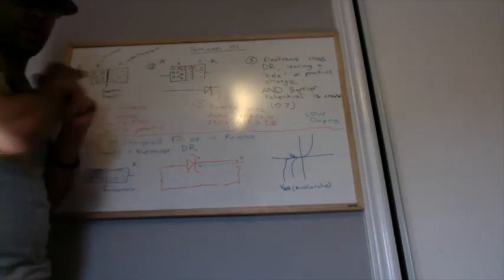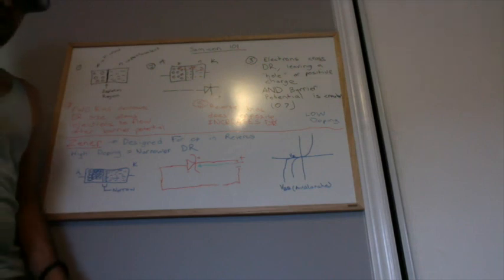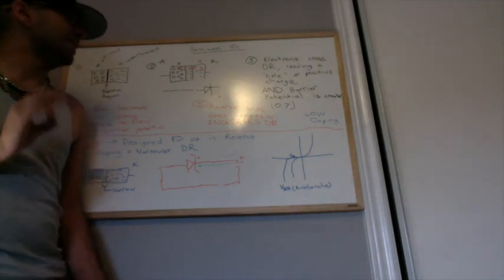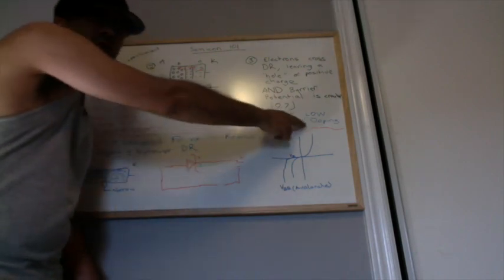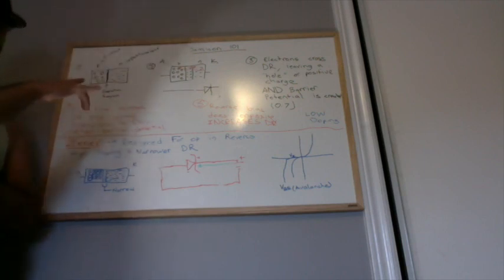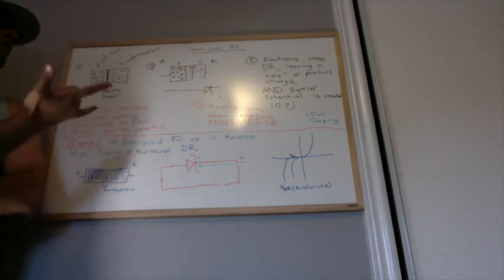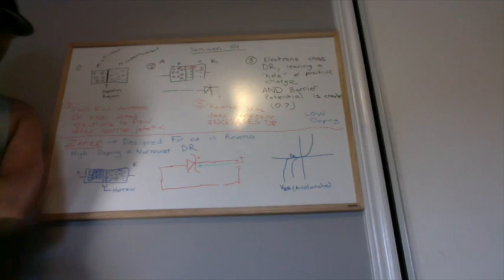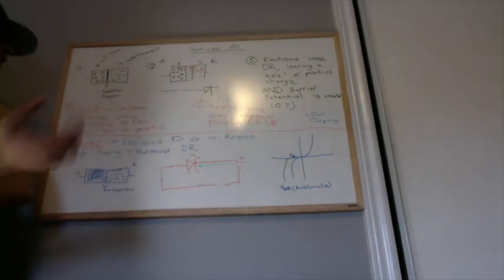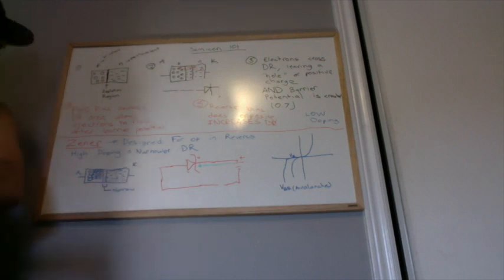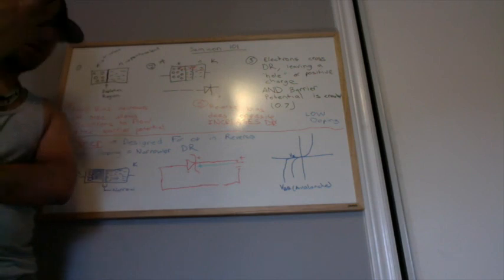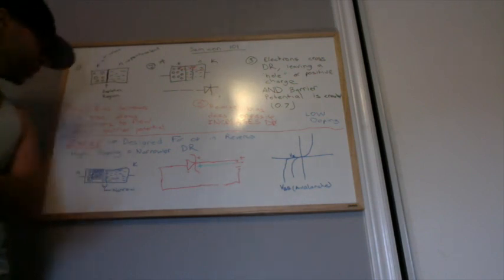Now, regular diodes compared to the Zener diodes, the big difference in terms of physics and construction is that they are lower doped. It takes fewer impurities, trivalent and pentavalent, for the construction of the P and N substrates in a regular diode. Now, a Zener diode is very highly doped, and we can follow from just logic.